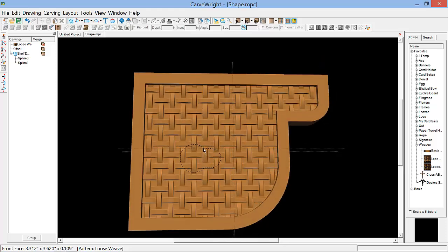Now, this is the hole that I was going to use for the dowel that goes through and holds the paper towels. And what I was going to do was turn, this is just over an inch and a quarter. It's about an inch and 1.3. And I was going to turn an inch and a quarter dowel, and then on the inside of the dowel, between the ends, I was going to turn that down to 3/4 of an inch, so the 3/4 of an inch part just drops down inside this smaller arc here and locks the paper towels in so it can't move.